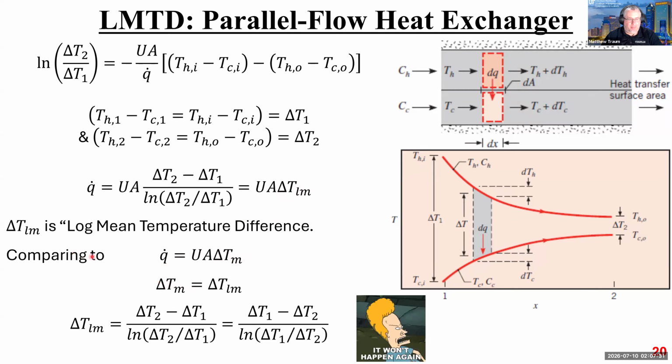So through that comparison, I'm able to eliminate everything else and recognize that this is sitting all by itself, and that is equivalent to this, which is from the equation that we started with when we were interested in heat transfer and average temperatures. So the big takeaway conclusion is that delta T_m is equal to delta T log mean.